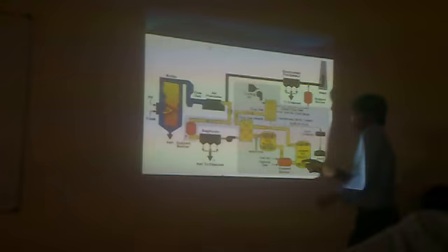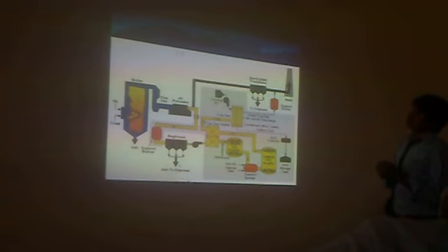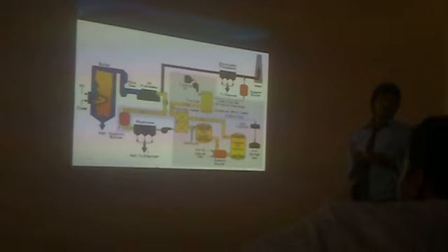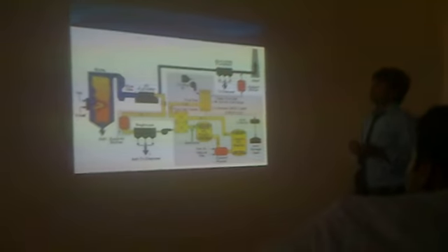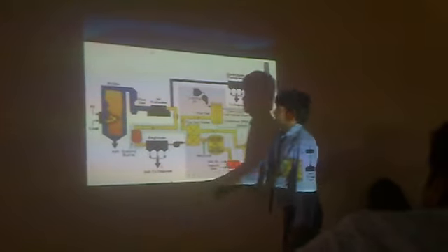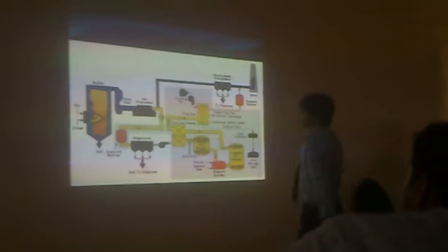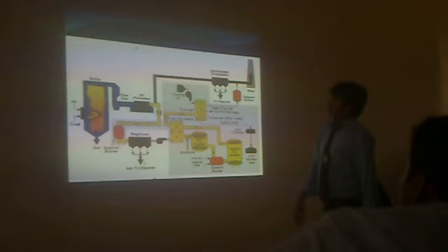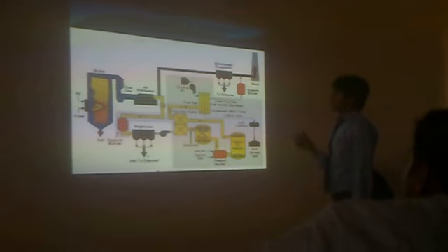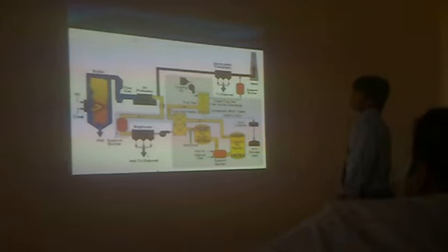When the ash comes in touch with the anode and cathode, it is deposited on the cathode and anode plates. Afterward, with the help of the vibrator, we collect that ash and dispose of it. Then the flue gas comes. NOx, nitrogen oxide, sulfur oxide, H2S, CO2 and CO gases are produced when we burn that coal.